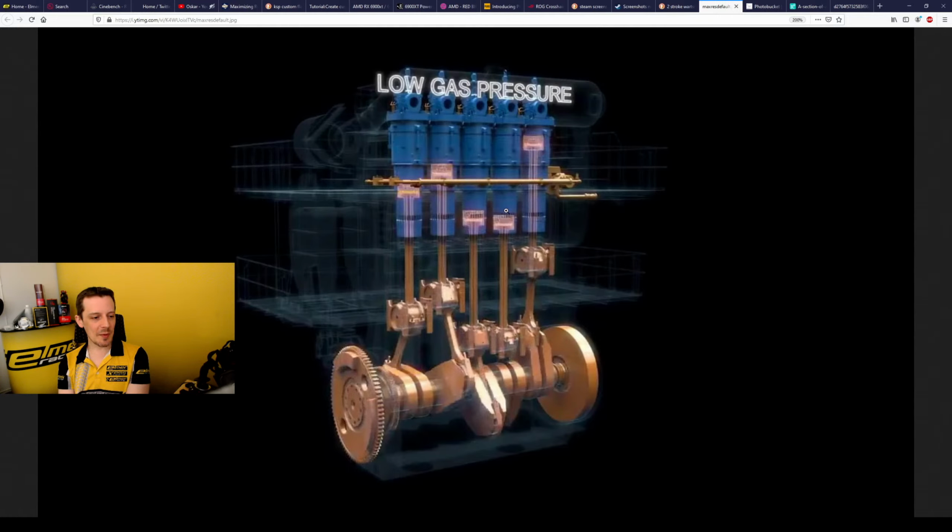And with these types of systems, you have these insane stroke to bore ratios. I'm assuming this is actually pretty accurate, so this might even be from some real CAD file, and not just some artist's impression or something like that. You can have bore to stroke ratios of like 3 or 4, and then you just flow intake air through there and flush the whole cylinder basically, and time the exhaust to close correctly, so you're not wasting energy there.